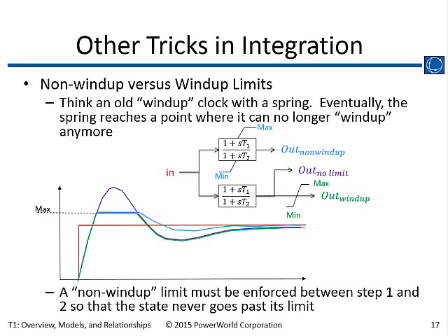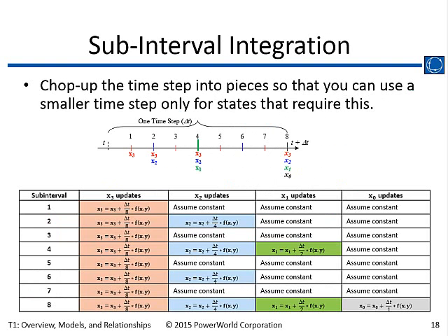We recently ran into this testing PowerWorld versus PSSE versus PSLF on how hydro governors' limits were enforced. It turned out that in some packages they were allowed to wind up, and that had a tremendous difference on the output. So WECC addressed that, and it's been taken care of. But it had a major impact on the output.